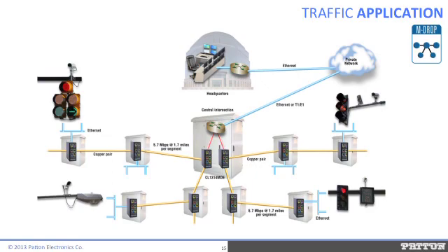To monitor and control the system, engineers can access not only the control box, but each individual device over the IP network from SHA. The greatest challenge to IP enabling a legacy system involved cabling issues with the distance limitations of standard Ethernet. Even though Ethernet technology serves as the backbone of IP connectivity today, the standard is limited to a maximum reach of just 100 meters, about 330 feet, per network segment when operating over Cat5 or greater cable.